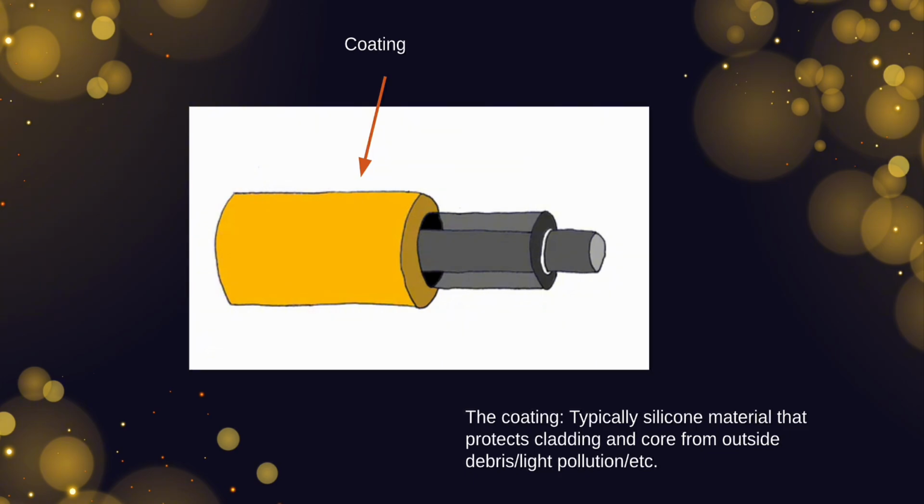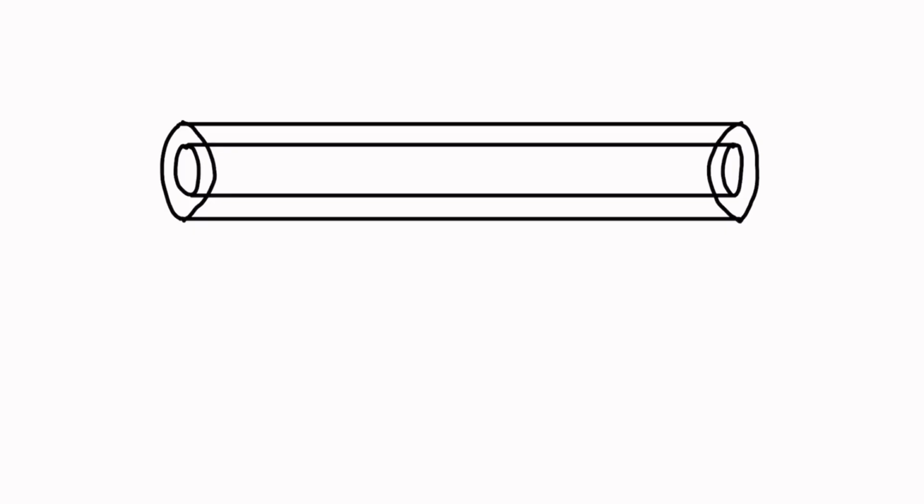inside the fiber. Imagine the innermost tube as the core of an optical fiber. Remember that it is a tube of solid glass-like material. On the outside of this core is the layer of cladding we talked about earlier. Now let's imagine a device sending out a single ray of light into the fiber. When it hits the edge of the core, the light refracts. We talked about refraction in a previous video, which you should watch if you haven't already. The link is in the top right corner.